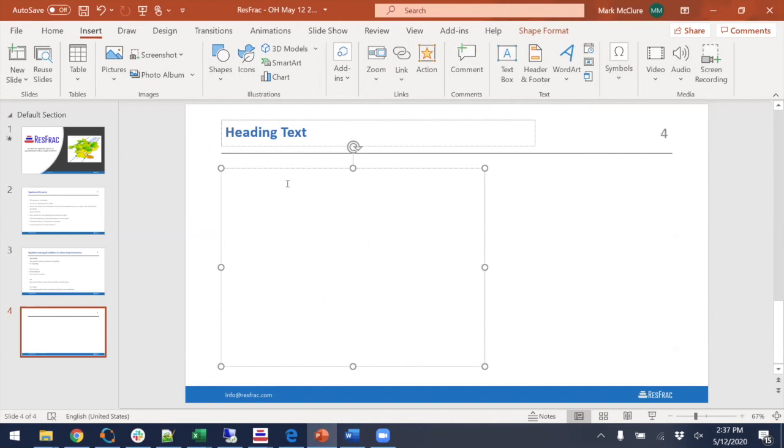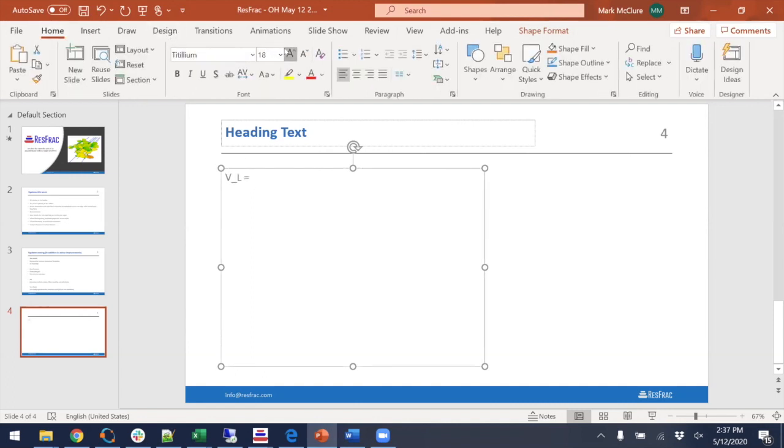So I'm trying to find the insert equation here, but I don't know where it is in PowerPoint. But the cumulative volume of fluid that's leaked off, if you assume Carter leak off, which of course is not always Carter leak off, but it's a good starting point, is 4 times A times the leak off coefficient times the square root of time.